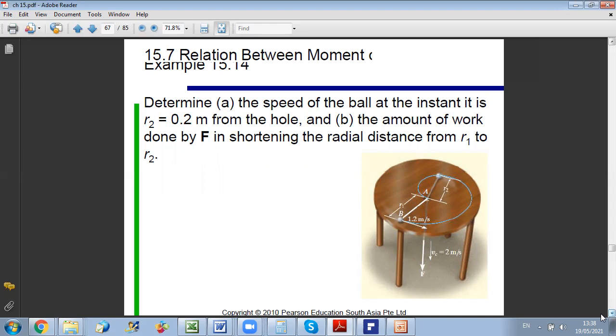So if r squared theta dot is constant, at any value of r I can compute theta dot. Then I have theta dot, and from work and energy I get the velocity, so I have v and theta dot, and I can get r dot, because v is decomposed into vr and v theta. That is how you should have solved it in the exam.